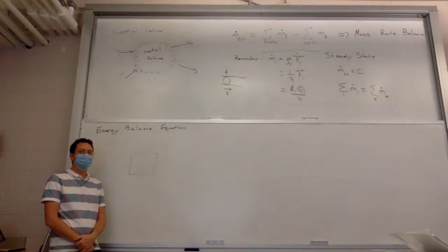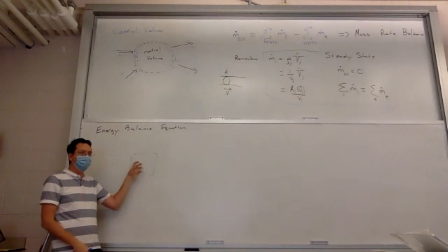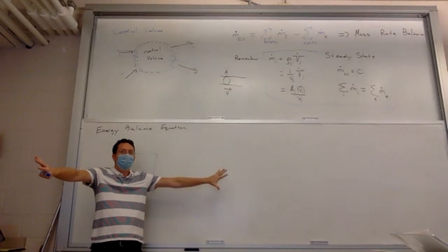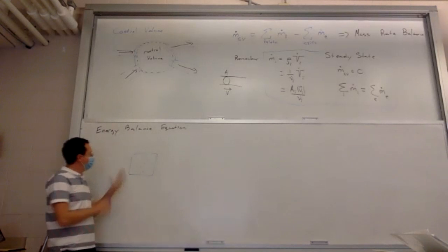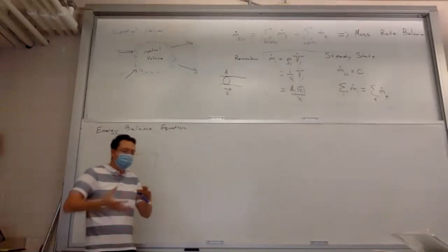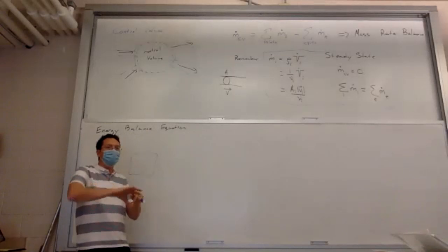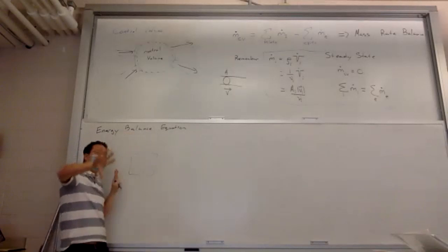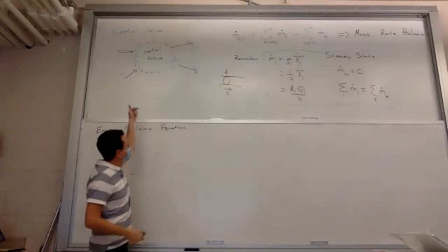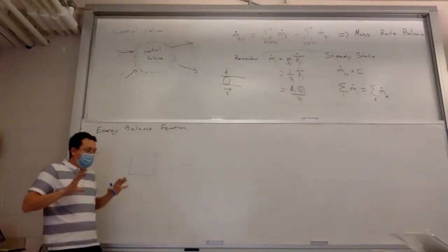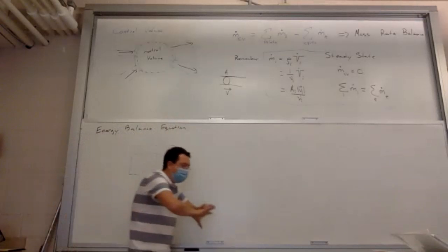It's not just the internal energy, because you not only have to have stuff there, you have to make room for it. You have to push everything else out of the way. Not entropy, enthalpy, right? Remember, the difference between internal energy and enthalpy is the energy that's in the thing, but also the energy needed to make room for it in the universe. So we're going to be continually adding and subtracting bits of mass. That means that as mass goes in, it has to push other stuff out of the way.